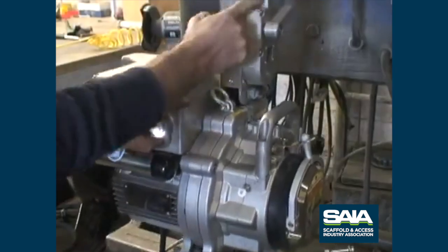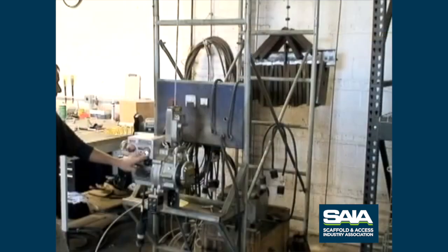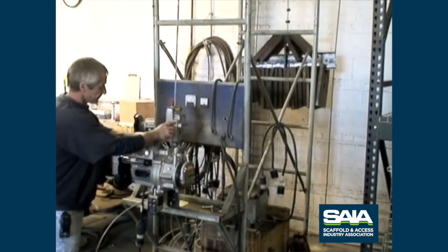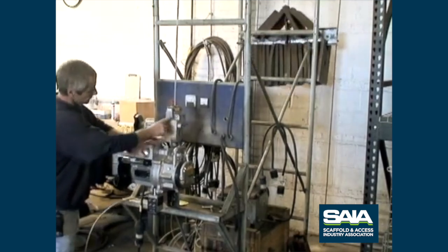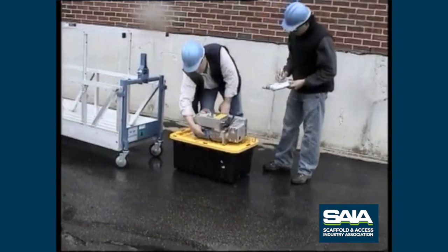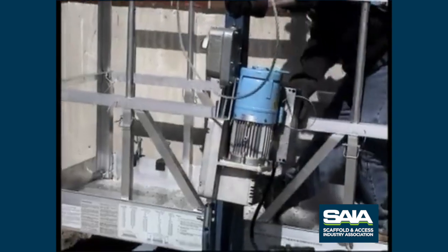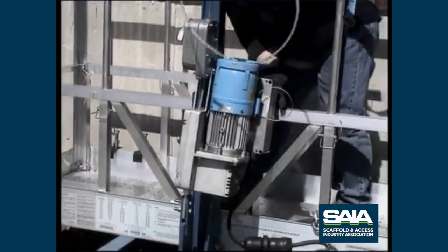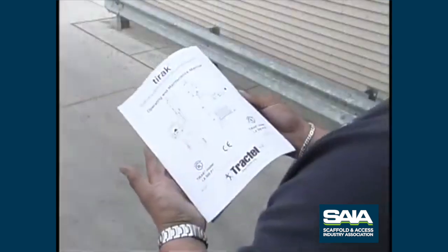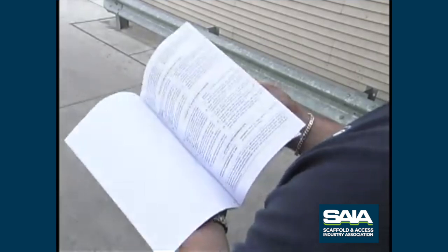Use only hoists that are tested and classified by a qualified lab. Be sure the hoist has been completely load tested prior to use at the job site. Once the hoist has been received at the job site, inspect all critical items to assure they've not been damaged during equipment transit. Refer to manufacturer's instructions for daily inspection and testing.